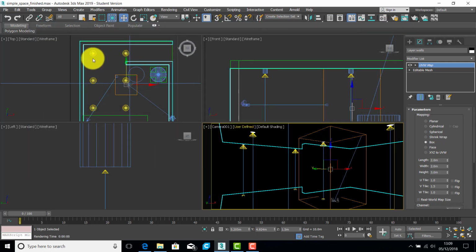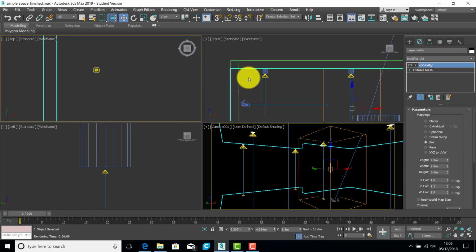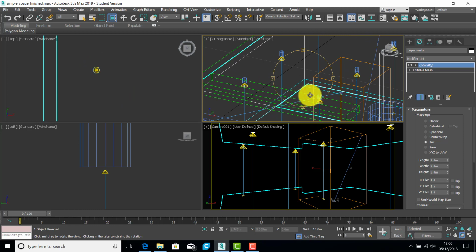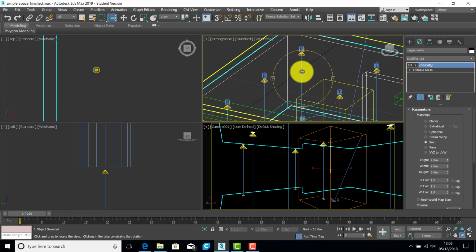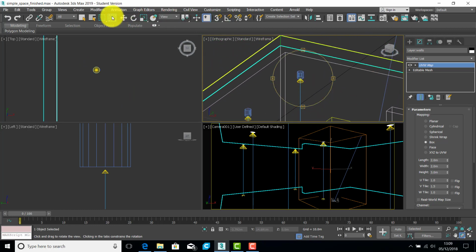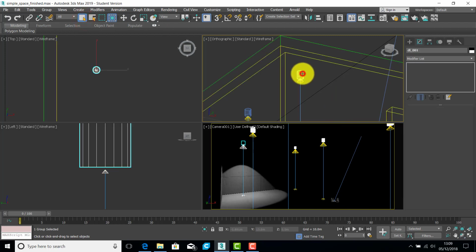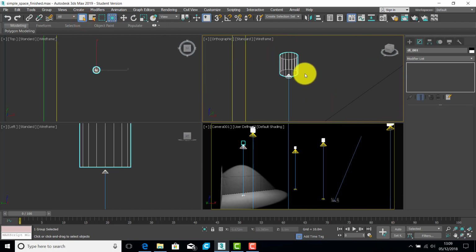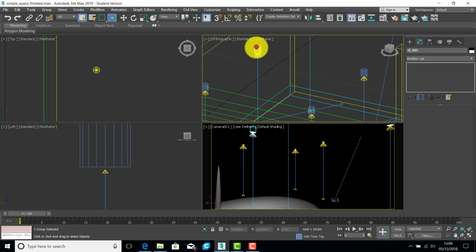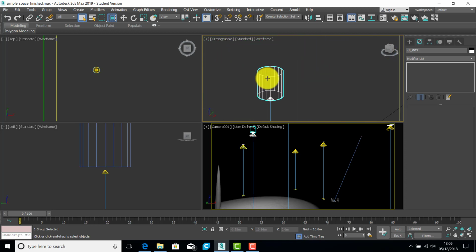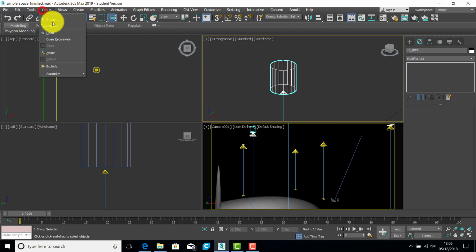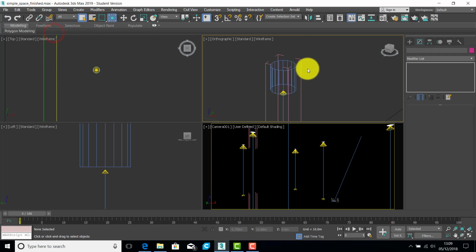Okay, then any changes you want to make, all you need to do is open one of the groups. So I'm going to just flip around so I can see which group it is I'm picking. Okay, and I'll go for this group. It happens to be the first one. It doesn't matter if it's the second one. There's the fifth one. Okay. Do group, open. See the pink wraparound indicates that it's a group.